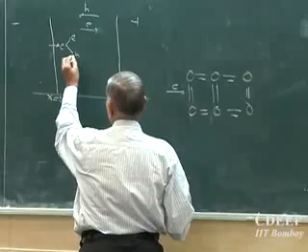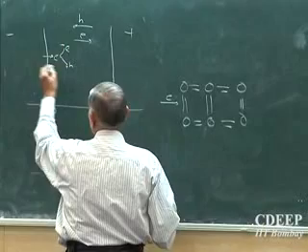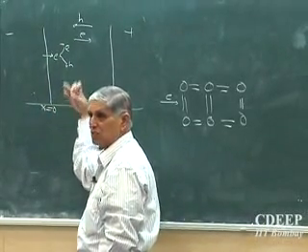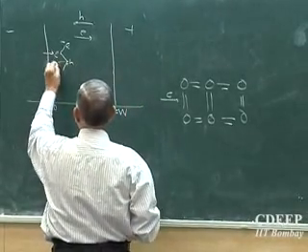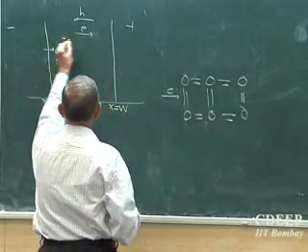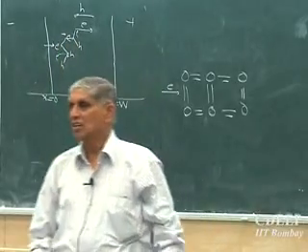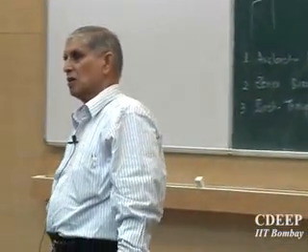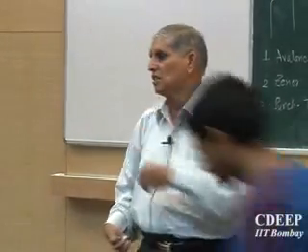Now these holes which are coming here, let's say plus and minus again, will try to go this side, and when they do they will also see the electric field and acquire energy, and may also create electron-hole pairs. Similarly, this electron, when it moves further, may acquire enough energy and can keep breaking bonds. This is like a cascade effect. So what is happening is 1 creates 2, 2 creates 4, 4 creates 8, a geometric kind of progression.